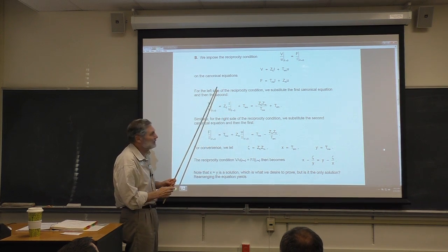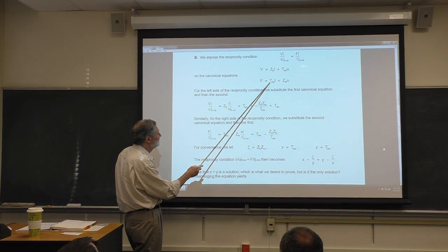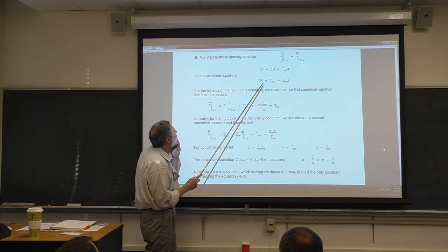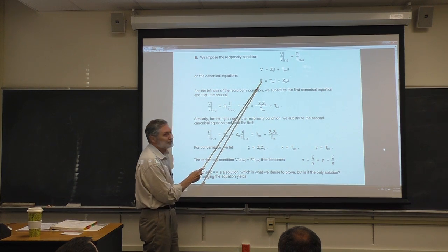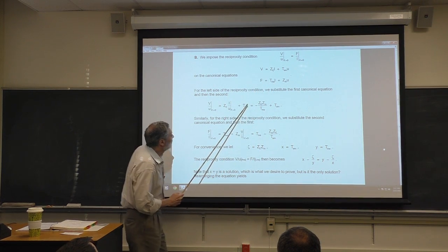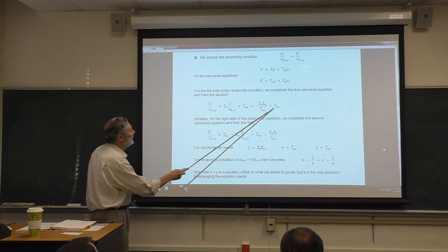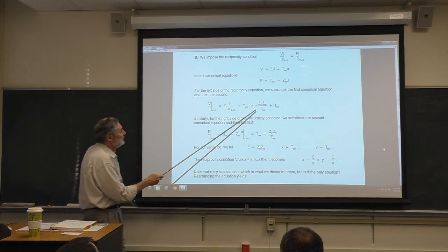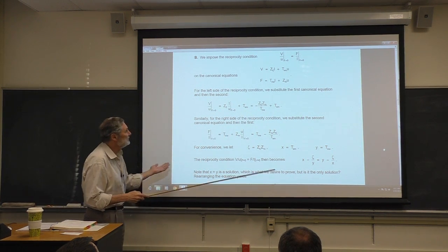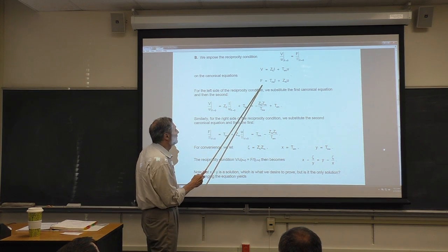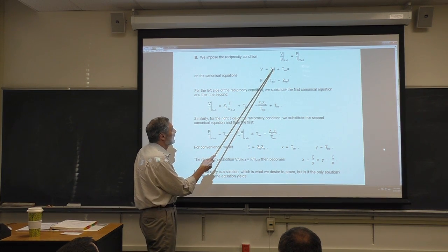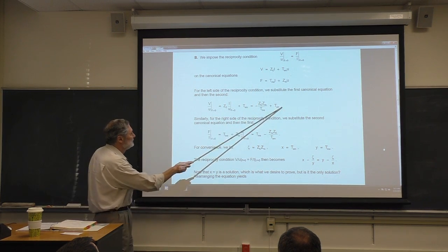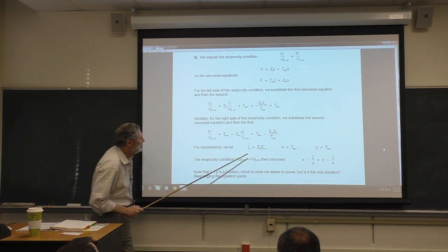So how do we handle this? Well, it doesn't take you long to figure out. You got to look at the next equation. Form the ratio I over U for F equal to 0. So you can see we can find that ratio. We substitute it in, and now we've analyzed the left side of the reciprocity relationship. Okay, we get this. You do the similar thing to the right side. You take the force divided by the current for no voltage. Find the ratio from this, very similar. All right, and you get this. And then we set those 2 things equal, and we get this.